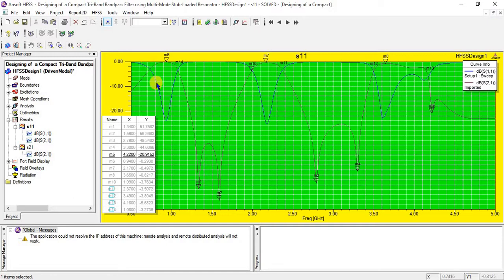Any change or signal coming out in the passband. Insertion losses must be found during the passband, the S11 passband. This is the passband of S11. These insertion losses are calculated here. That is why I have selected the maximum point of this graph from here to here. It shows the losses as a result of insertion of load in a passband. Similarly, this is M6.